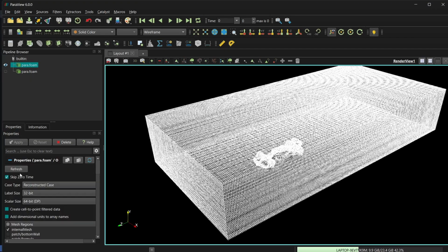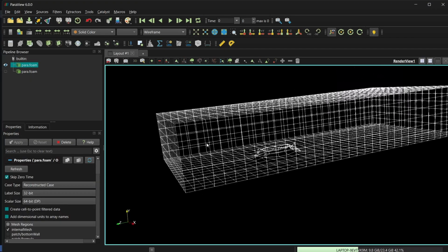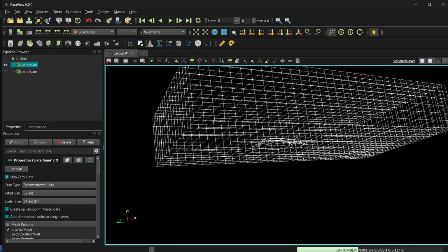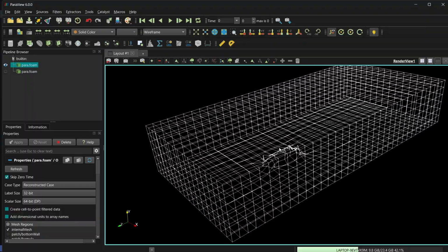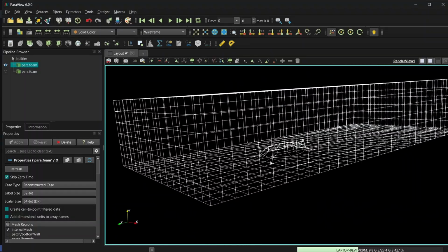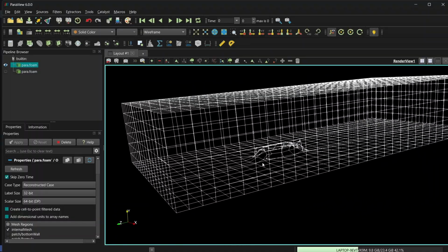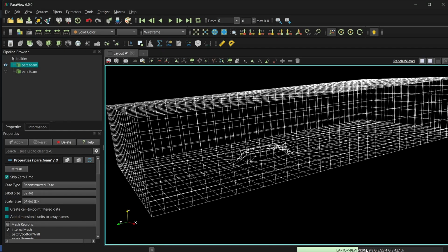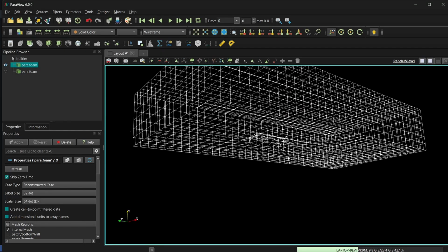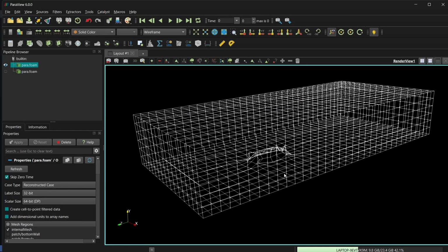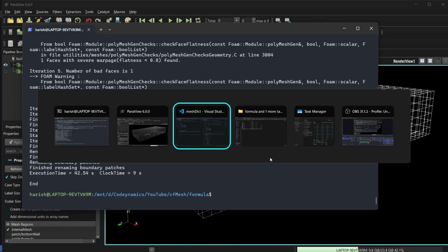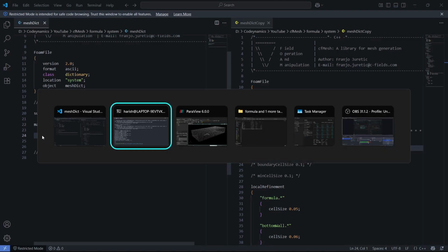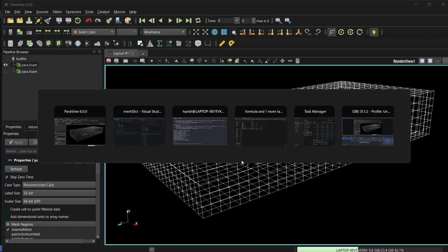Okay, it's over. Now I think this size is okay for the free stream, maybe for a tutorial. If you're working on validation, this might not be okay; you might have to go smaller. As you can see, my RAM is also only 24 GB, so I'll try to keep it to that level. If you want an even finer mesh, you can learn the procedure and then do it as you wish. Now what we are going to do is add local refinements specific to this formula patch.